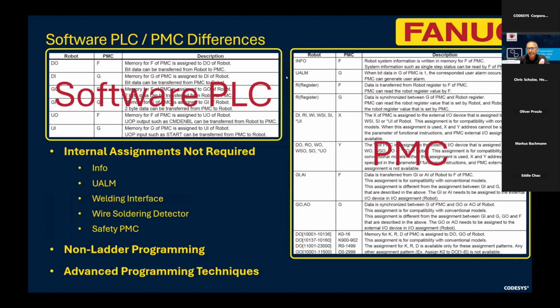Software PLC is the perfect option for advanced programmers who do not require PMC internal assignments such as info, user alarms, welding interface, wire soldering detection, or safety PMC. In those cases, users can still use the PMC software. However, users must choose between the two because both are not supported at the same time. However, if users want to program non-ladder and use advanced programming techniques, then software PLC using the CODESYS development system is the perfect solution.